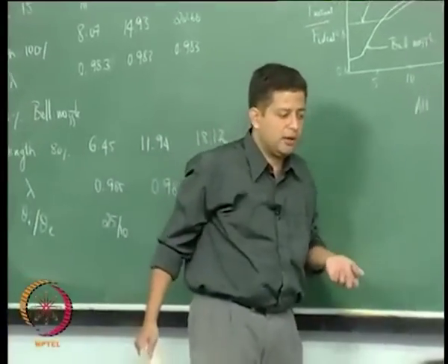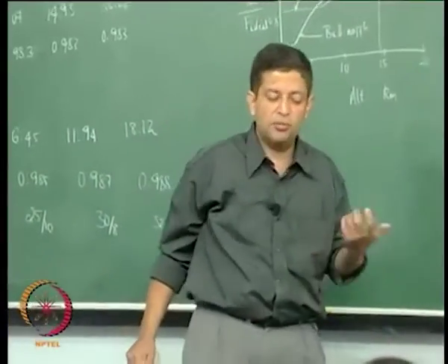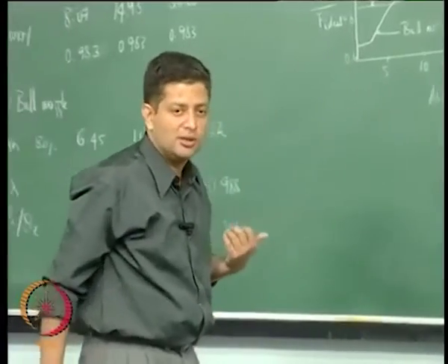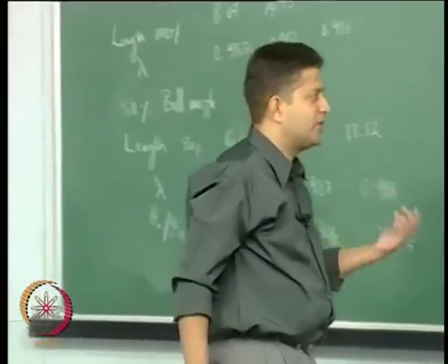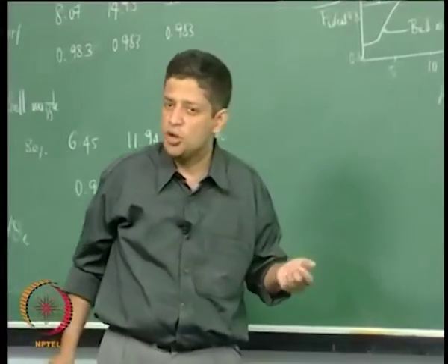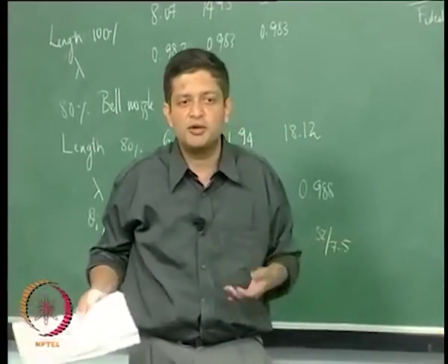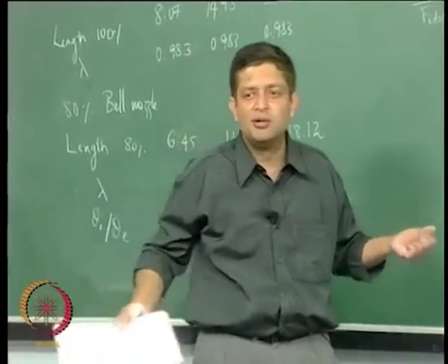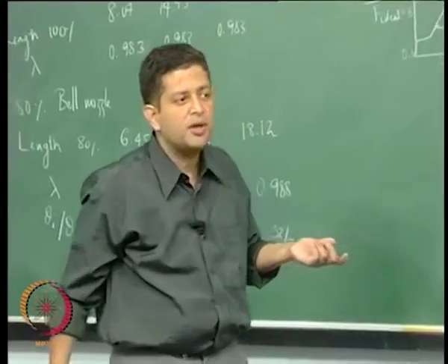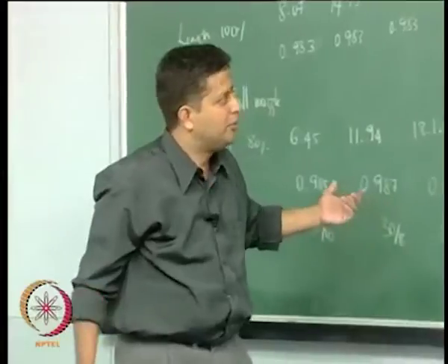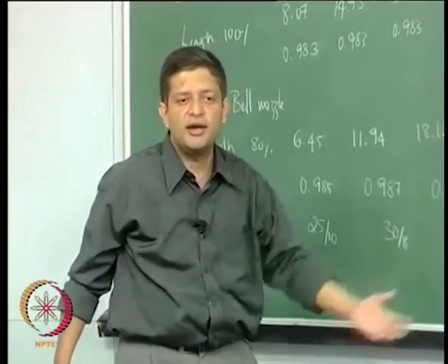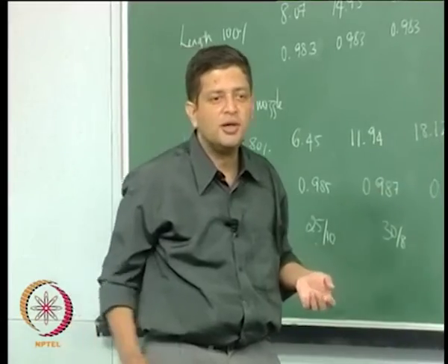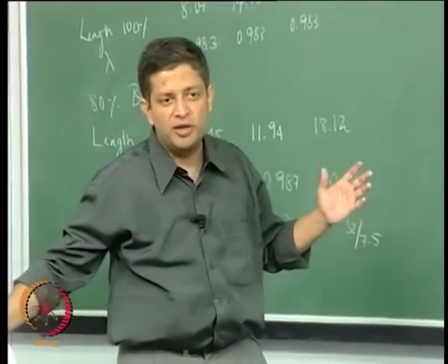Also, if you look at the rocket motors that are typically used in the lower altitudes, these are usually solid motors, and the pressure in the combustion chamber is not very large, this is around 70 or something, and you can expand it only to around 1 atmosphere or so. So, what you would do is you would have a conical nozzle, whereas if you look at high altitude motors, they can expand to vacuum, near vacuum conditions.